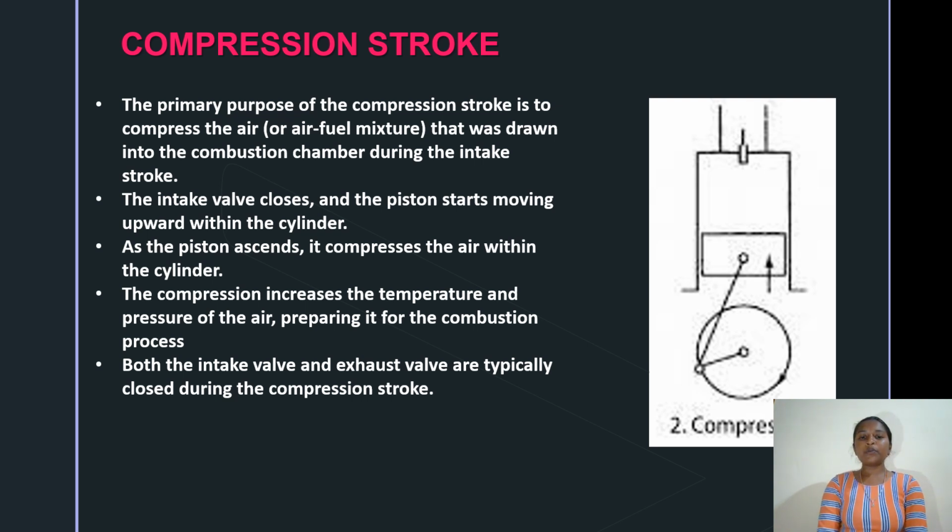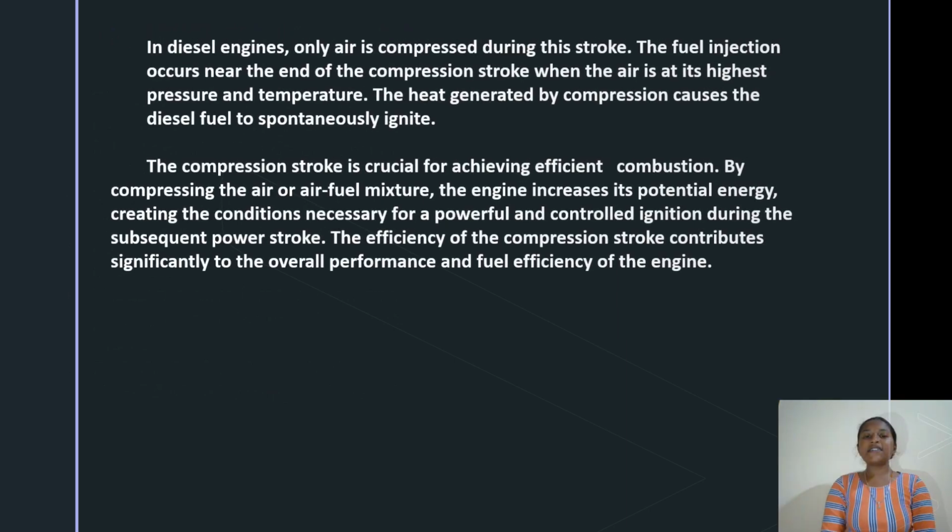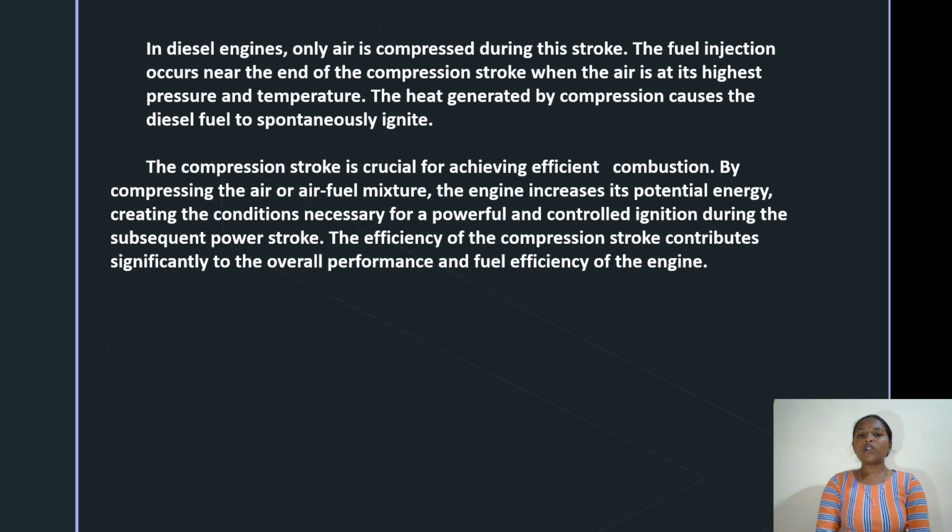The piston movement upward increases the temperature and the pressure of the air, preparing for the combustion process. Both the inlet valve and the exhaust valve will be closed. In diesel engine, only air is compressed during this stroke.